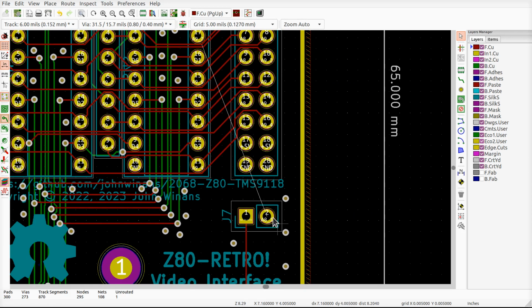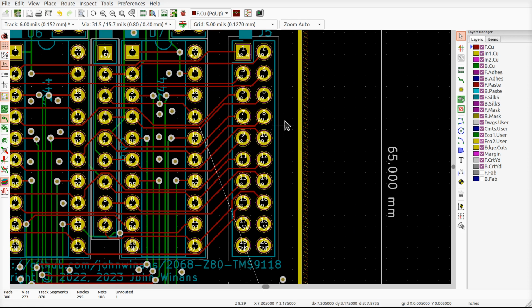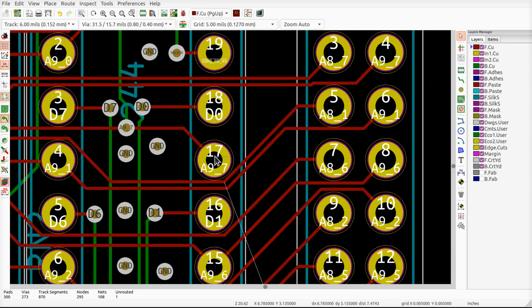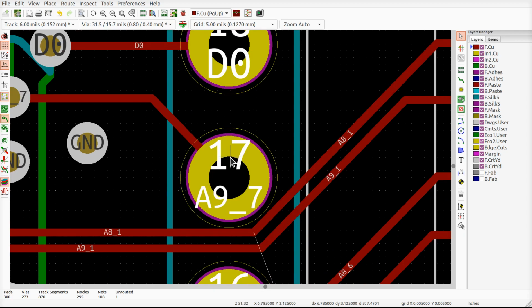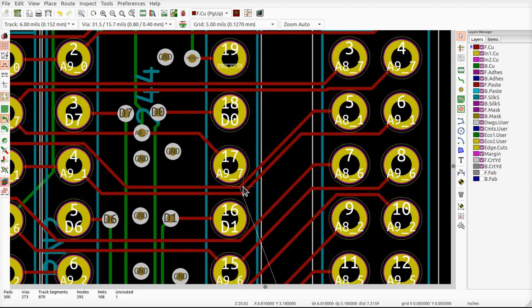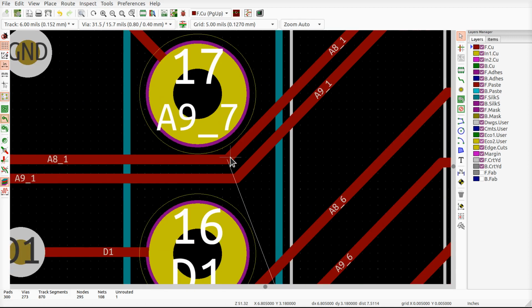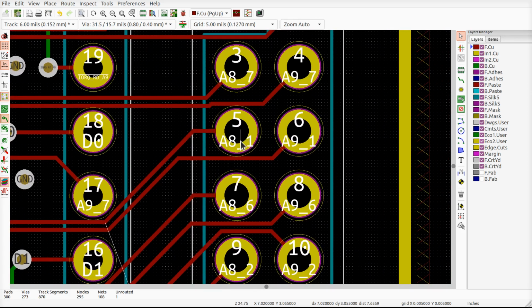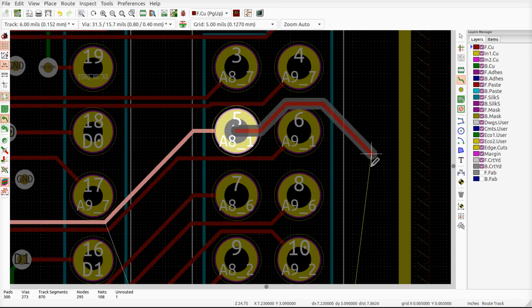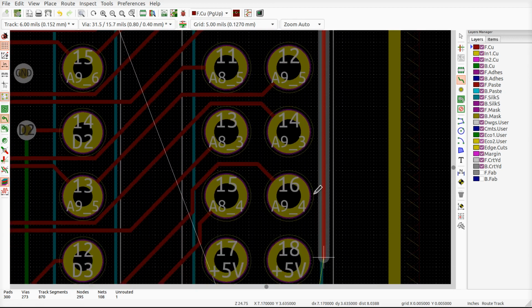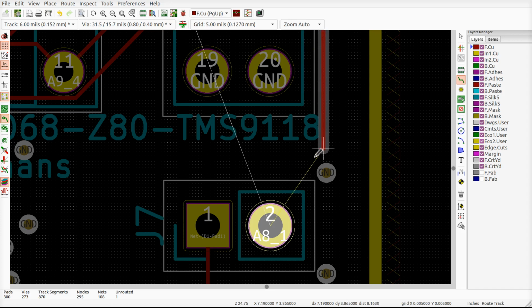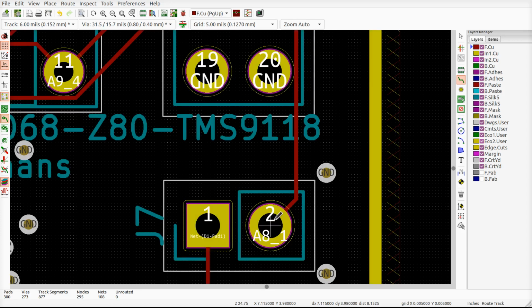All right, so what I'm going to do is I can just bring it up around the outside here and then go to wherever this thing ultimately runs off to, right? A97. Oh, no, it's not A97. It's going to this track right here, which comes up over to here on pin 5. So I can run a track out and around like that on the top of the board if I want. Come around down in here. Do one of these moves.